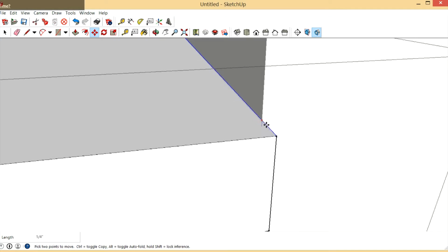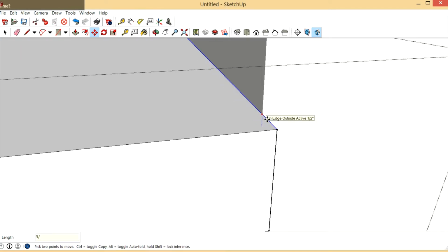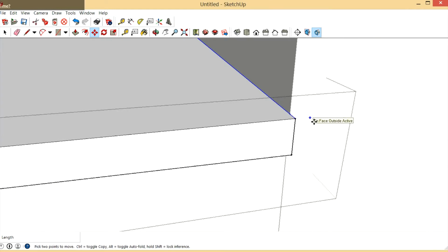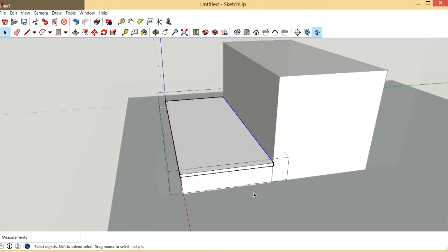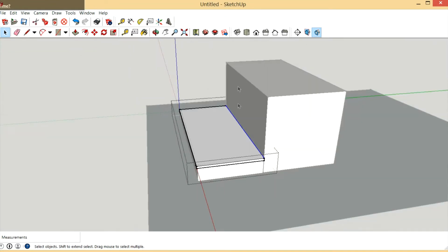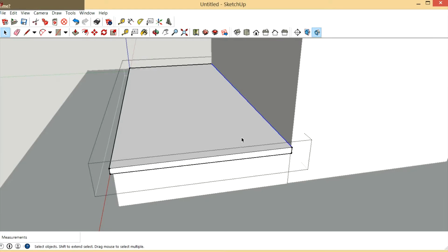There we go. Now I'm going to move it up 3/4 of an inch, and that's really not much. Not much that you can really see, but if you've got an overhang on this house and water's falling off and dripping on it, you want the water to run this way, not back towards your doors or your siding.